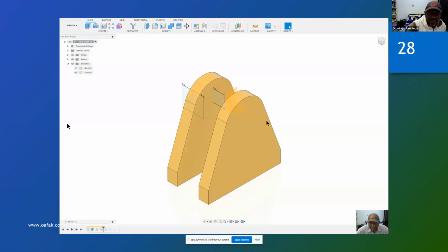So starting from the extrusion, and then after creating this drawing on the ZX plane, you are going to do a revolve, and then when you do the revolve, you are going to choose the axis of revolving, axis of revolution, and you will see what those two things will do.